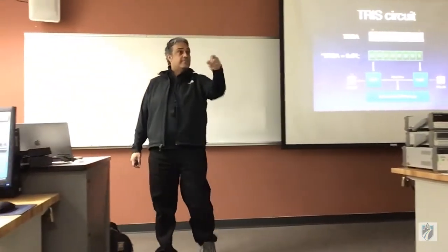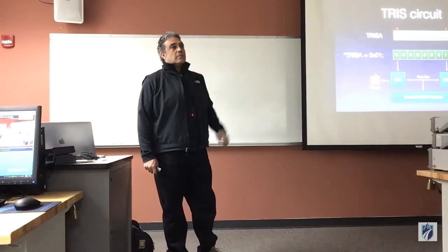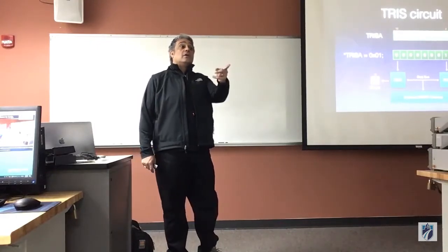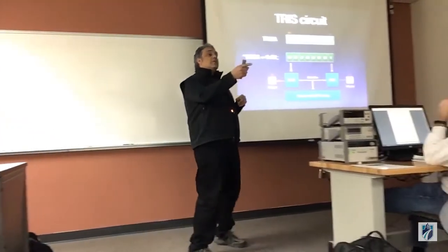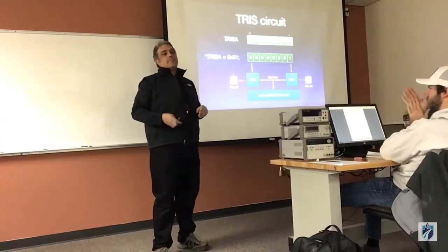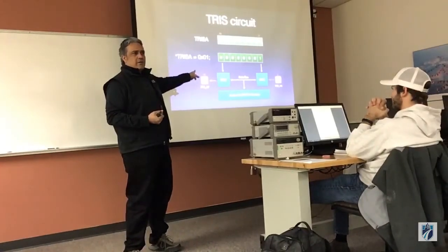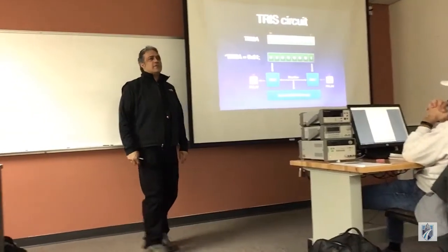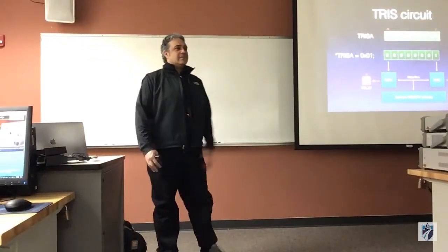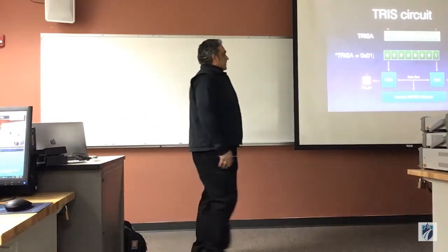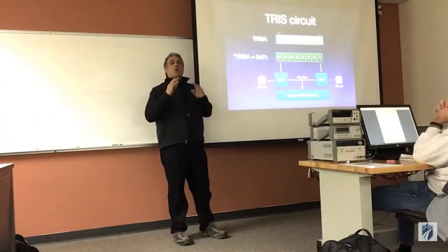See that? So this would be more like me coming from doing Arduino programming. This would be more like an input. It's reading a signal and it's outputting a signal. Well, let's take from the Arduino world. From the Arduino world, there are some registers called DDR. Heard of it. And so the DDR register is what the TRIS register is here. They just changed their names because they're competitors and they don't want to have the same name. It's dumb. They should have called it DDR, but they didn't. They call it TRIS. But that's the data direction, right? It's all about data direction.